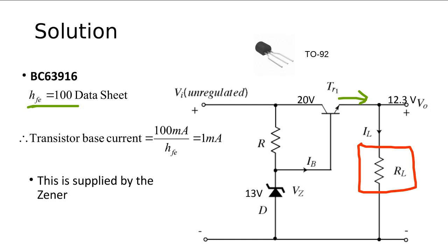This transistor, you go back to the data sheet, it's a 1 watt job. So if it is a 1 watt device, we already have approximately 7 volts across it by 1 watt. You know how much current it could handle, right? You just divide the wattage by the voltage. So the instant that current passes that load, this transistor is going to burn.